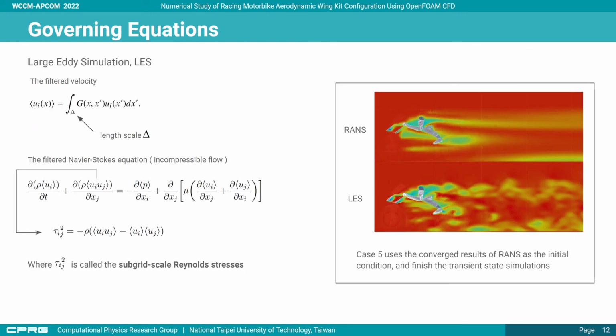Large eddy simulation, in abbreviation LES. The converged results such as drag coefficient and lift coefficient of the RANS turbulence model are applied as the initial guess value using numerical analysis method to initialize the LES turbulence model solving. In this model, the large-scale components of the flow field are filtered from the small-scale components using a wavelength criterion related to the size of the eddies.